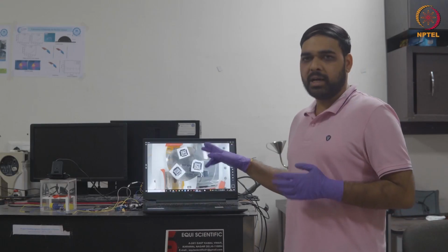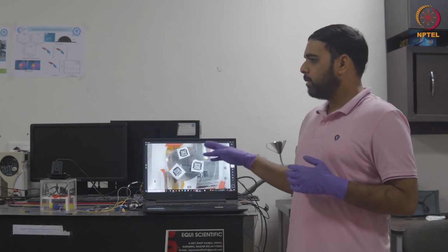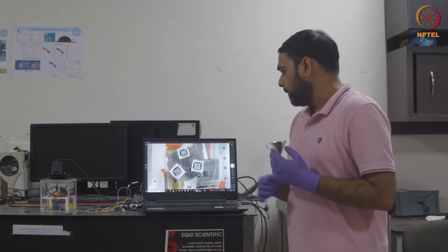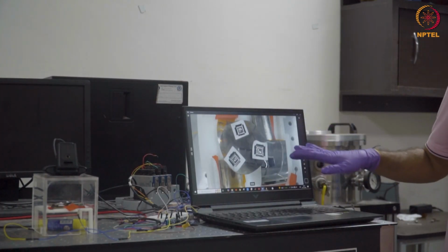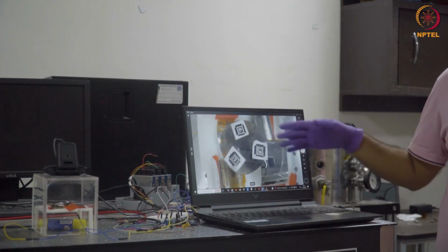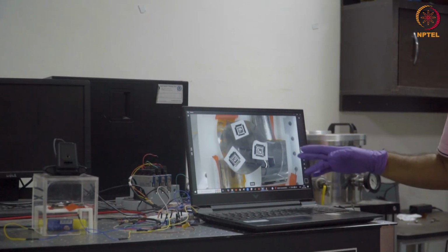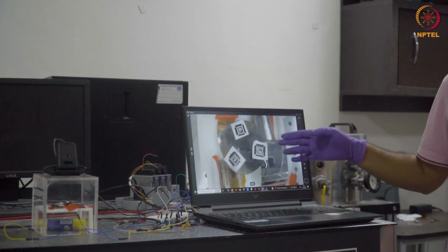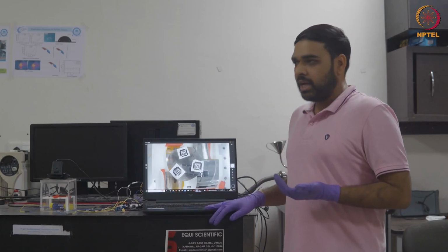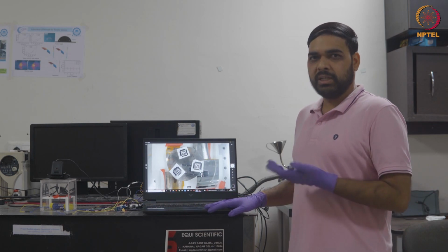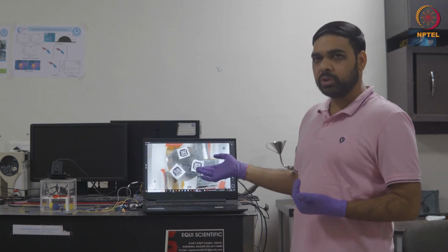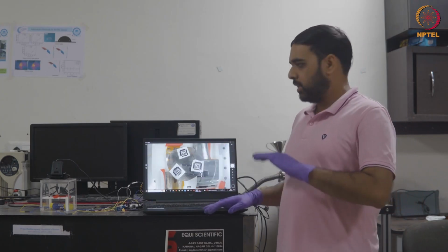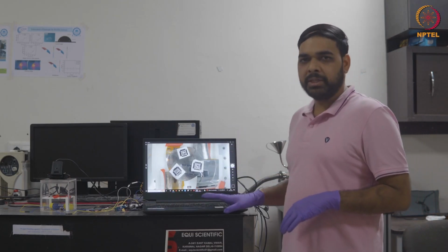So all the parts are NiTi SMA based, and they have been micro machined using laser energy by the fiber laser method. In this structure, the mirror is being moved with the help of the motion of these four actuators individually or in combination. So when we supply electrical energy to any one of the actuators, it will actuate in the forward direction, as we have seen in the electrical actuation video also. When we apply the energy, the actuator will move forward, and because of that forward motion, our mirror will tilt in the upward or downward direction according to the motion of the actuator beneath it.